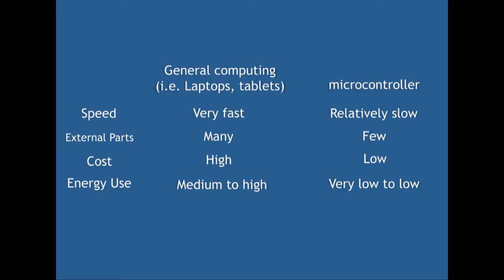Why should you use a microcontroller over a CPU? Well, this really depends on the application you are working on. We don't use microcontrollers in your personal computer because they don't have the processing power you need to run a full OS and multiple other programs. Like I said before, the microcontroller is for one single task, whereas your personal computer is running multiple tasks at the same time. This is what's nice about microcontrollers, is that they use very little power to run and don't dispense a lot of heat, though they are much slower than the CPU in your computer.